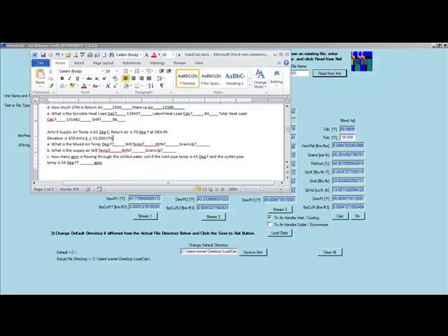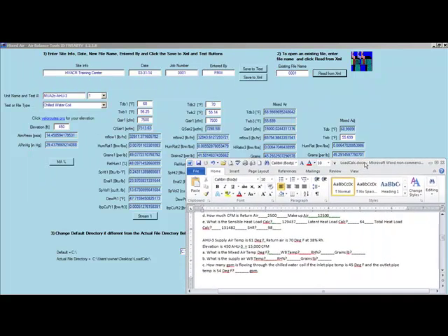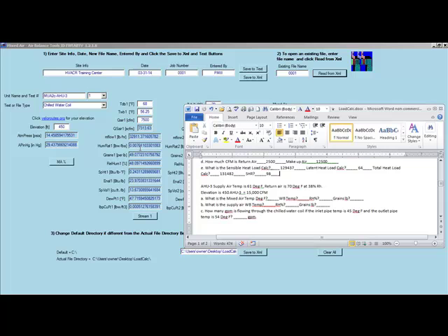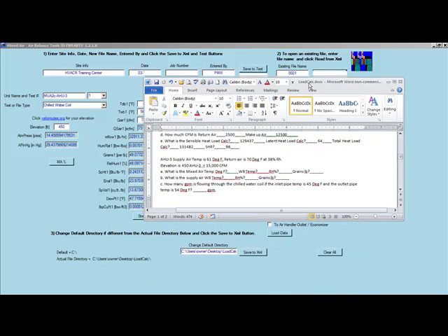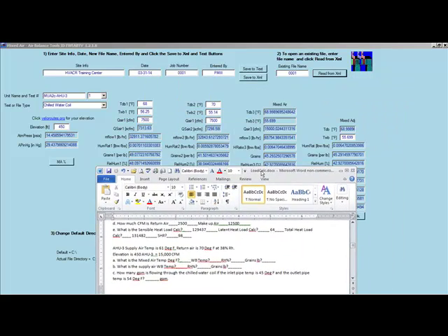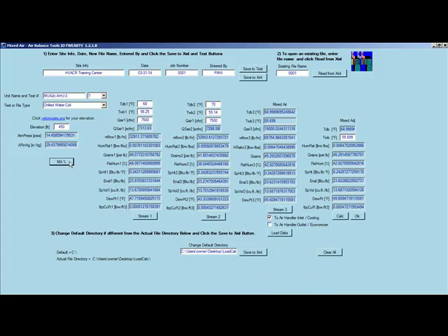So, air handler 3, the makeup unit is still the same, 68 degrees at 48% RH. In this case, our return is coming in at 70 at 38. So here we go. We got 70 degrees at 38% RH. We want to figure out our CFM. Let's do that first. So we're going to go mixed air percent.